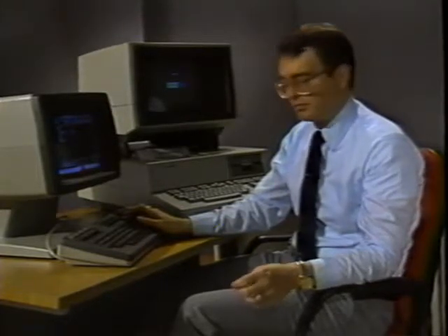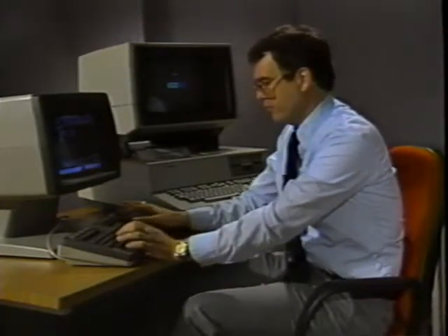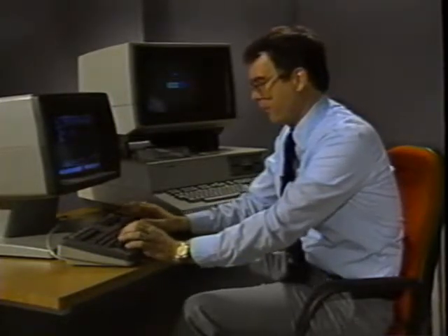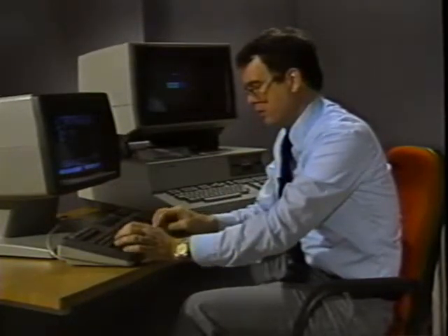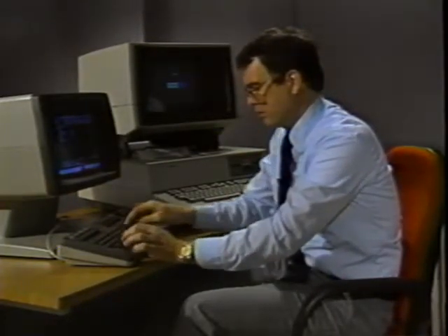I'm now ready to union this object together. In Menu Edit, I called forth the command Union, and I joined together the two flanges, the middle portion, and also the stem guide primitives, which you'll see coming up in purple.